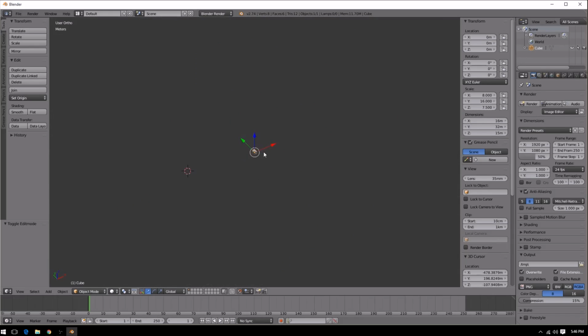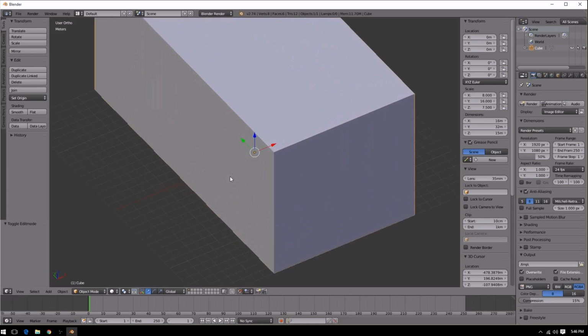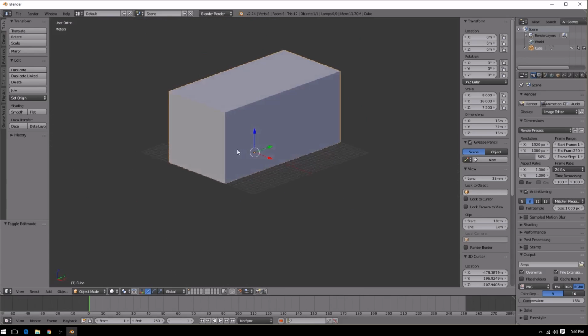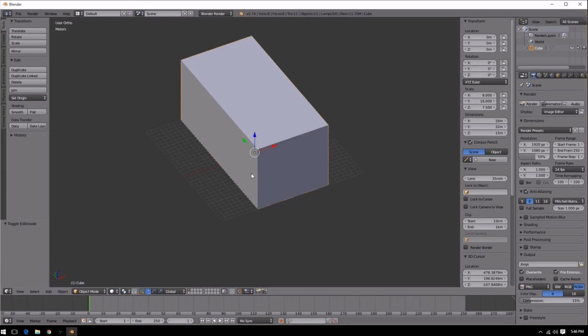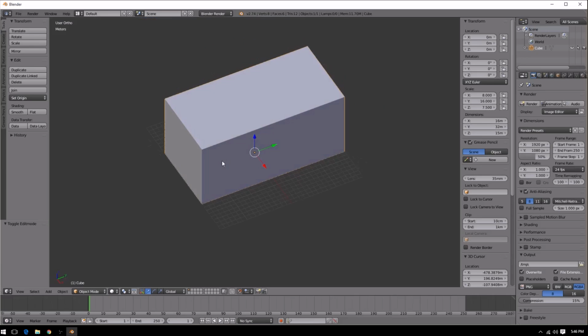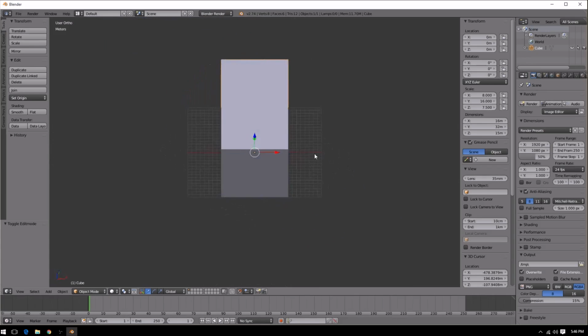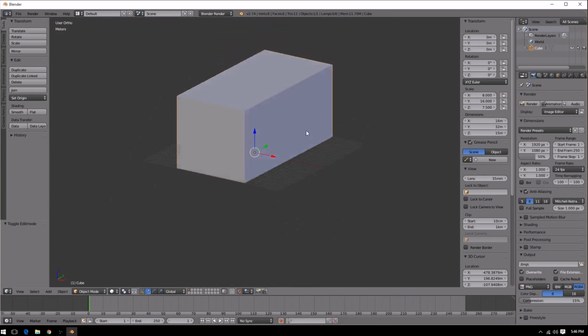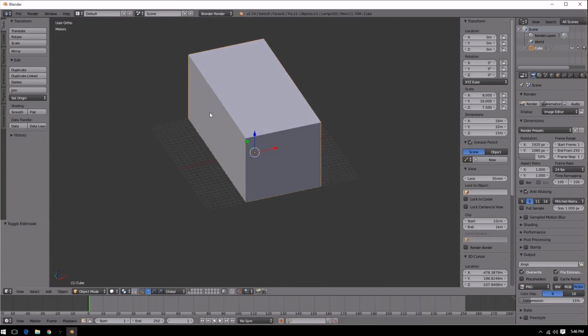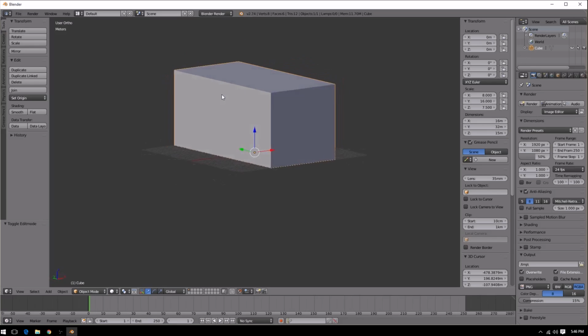If we were to look at this in game, you wouldn't be able to tell half the details we're going to add into it modeling. So the LOD needs to be a very simple structure that eventually will be UV wrapped, and the game can auto texture. Now, if you have a complex building, you're going to want to make your own texture. But for a simple building like this, we're going to allow the game baker to bake out the texture based on the UV unwrapping that we've done. That is moving far ahead.